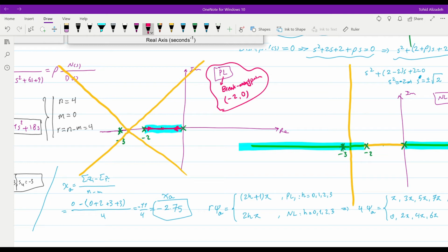On the other hand, we have two open loop poles at -3, and since the real axis around that point doesn't belong to the positive locus, the branches will depart from those poles towards the complex plane. They will not remain on the real axis for any time. So they will go out of the real axis and approach infinity using the two asymptotes that we have.